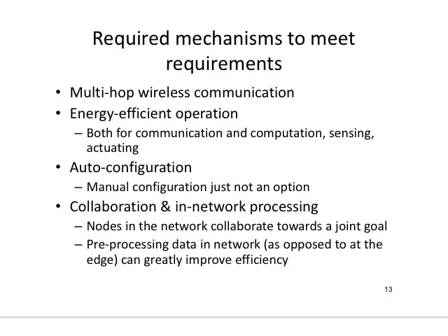So in-network processing can help you to answer complex questions and can also be a very effective tool to reduce the amount of information flowing into the wireless sensor network, right? Because you don't have to have every single node sending huge amount of information to the central point, because this will cause what? This will cause a huge amount of bottleneck.